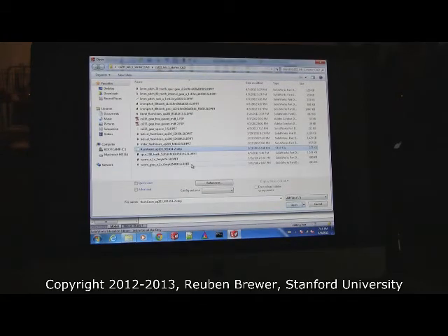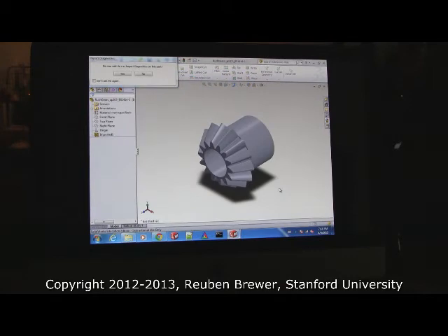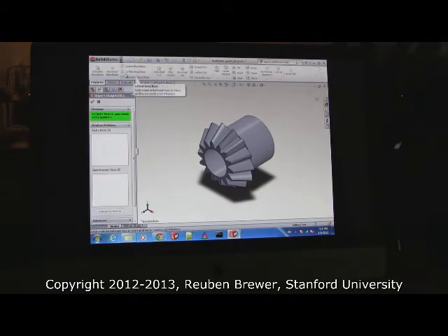Now I want you to click on the Rush Gears, and then it'll have a .step. Just so you know, there are a couple universal file formats that are non-proprietary to SolidWorks. They're .step, .stp, .igs, .stl. Anytime you see one of those, it means it's universal. So go ahead and click Open. It's going to say, do you wish to run import diagnostics? No, it is useless. Do you want to proceed with feature recognition? No. This is all stuff that SolidWorks does that is useless. Do you never use it, or we don't use it right now? Never. It's just totally useless.